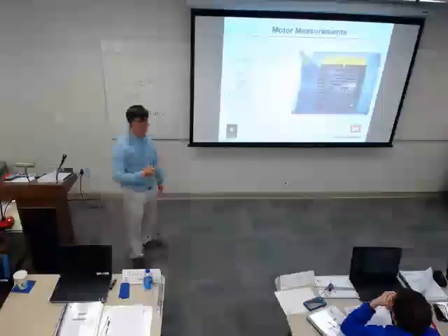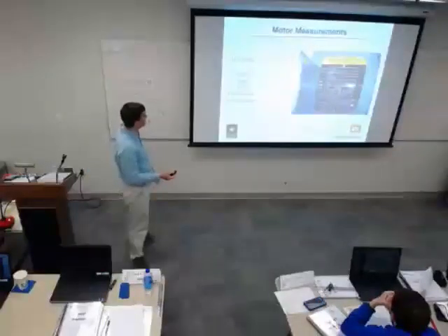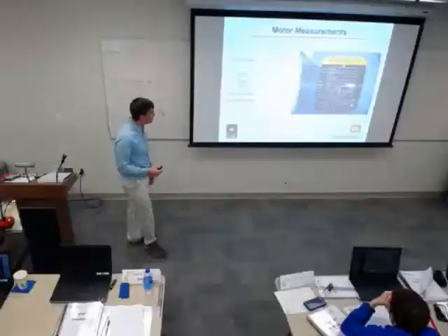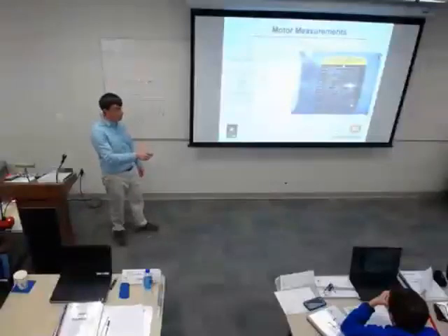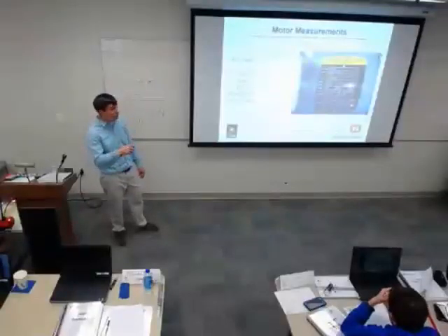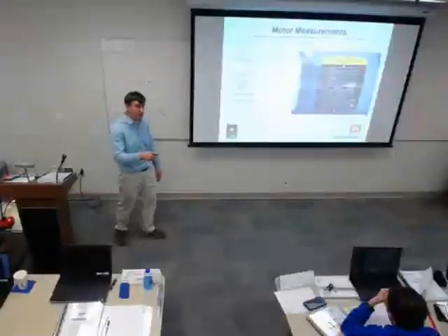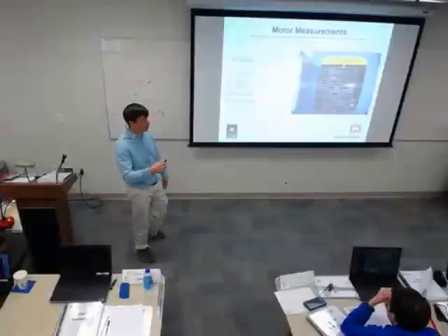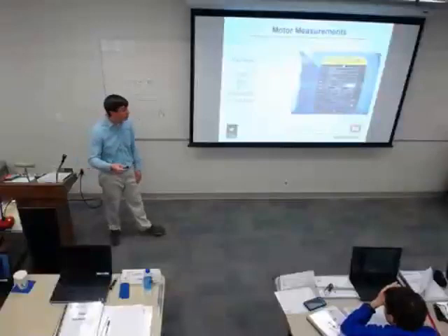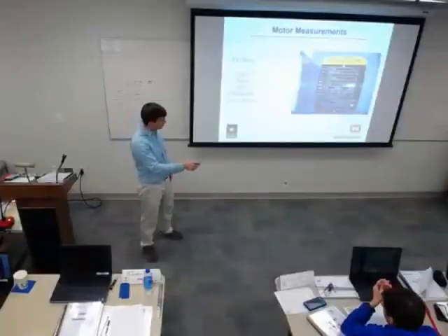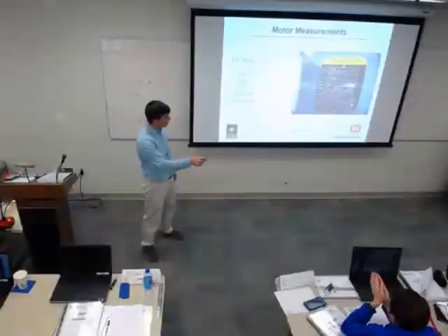Motor measurements, talking about that current going up. So what am I looking at? This is the same picture we showed you earlier. Submittal wise, I definitely want to check that I have the right motor in place, that it's big enough to handle whatever load I need. We saw on the system curve, the fan curve, what size motor I needed for that. That motor size should also be specified on your equipment schedule. You want to check that your horsepower rating is adequate.